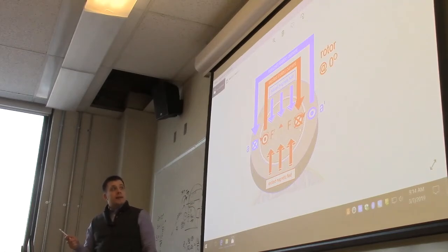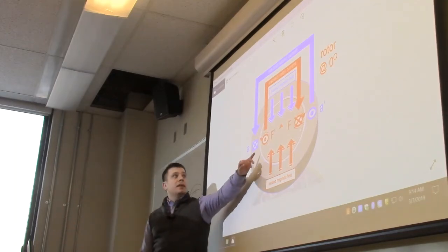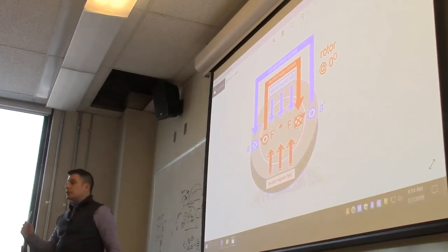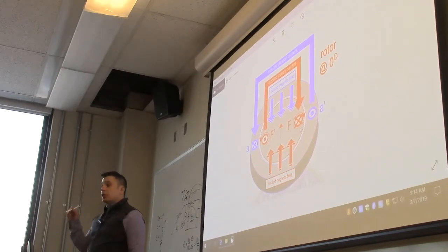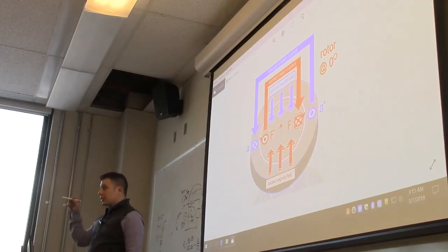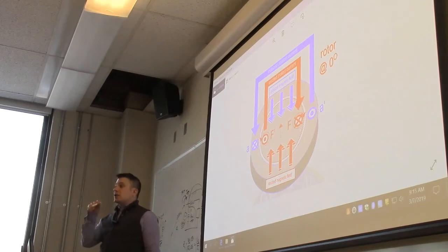Number two is that the strength of that current is not dependent solely on the field winding current, but also the rotation, right? Because no current is generated unless the magnetic field is experiencing a change, right? It's d phi dt, not just phi, okay? And so it's the rotation that actually provides the change in the magnetic field.